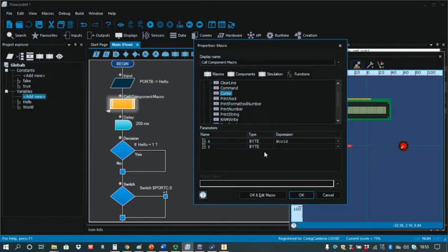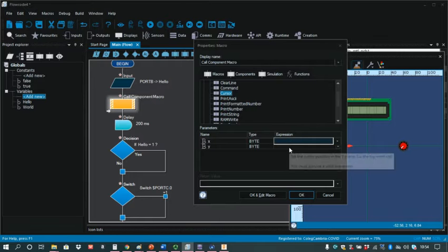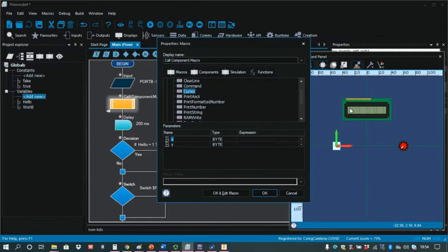We can move the cursor, and that usually gives us an XY value for moving the cursor. So for example, 0 is the top line and 1 is the second line on a 16-bit, and then for the Y, it's simply how many characters to the right that I want to shift it. So if I put in 1, 3, then it would shift it down to this line and 3 across.